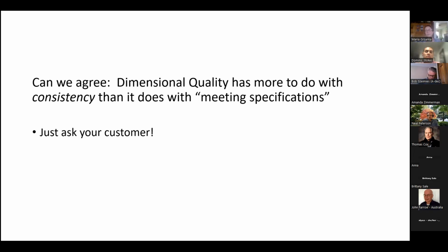That are "in spec," and sometimes they fit well and sometimes they don't fit well. That sounds like the spec is wrong to me, or else I don't understand what a spec is. No. So if you have a spec, and it depends on how they're specified, but it's very normal to have, if you do have a spec like that, a shaft and a bushing, if you have a part just at the very high end for the shaft and at the very low end for the bushing and put them together, they'll be pretty tight, depending on how they're specified.